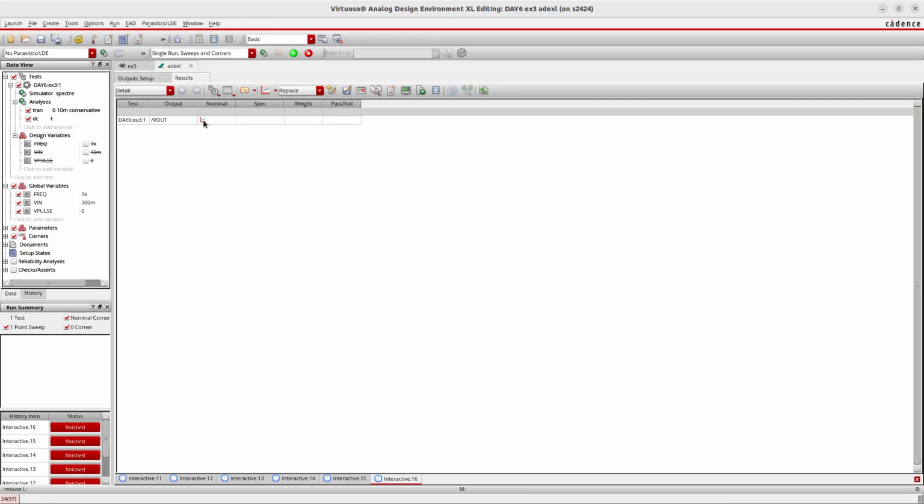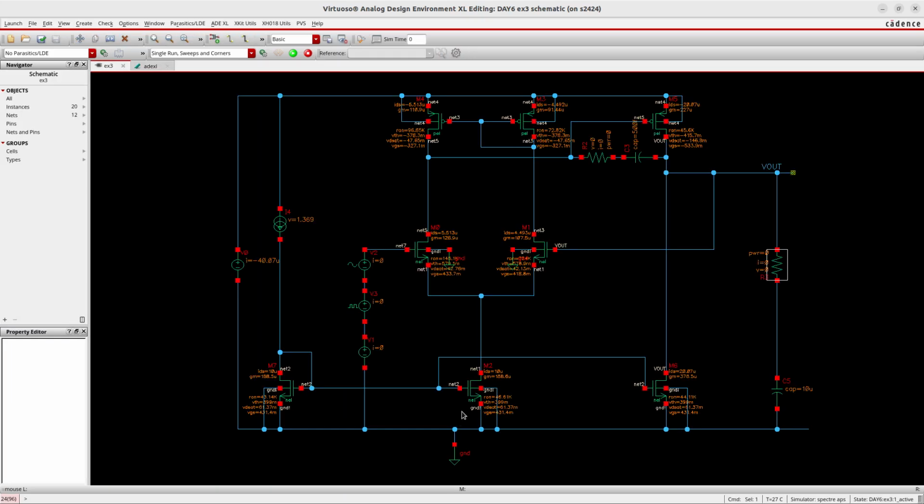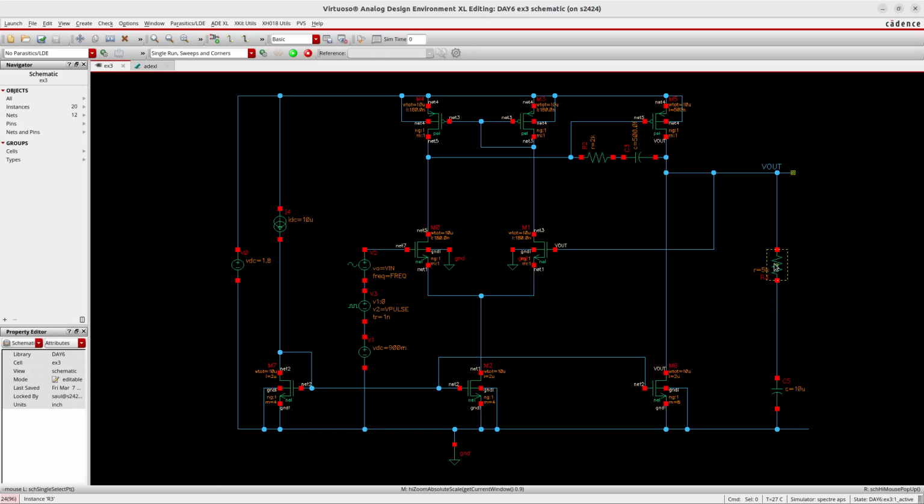It is 5 kilo ohms. So let's see, design defaults. It is 5 kilo ohms, and we can assume that this is just an external load to the chip. I have a decoupling capacitor to ground that is just stopping the DC voltage and currents. So for AC, this is going to work as a short circuit for AC signals.